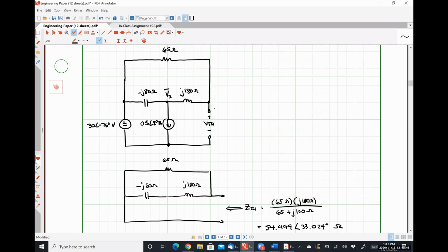So it looks like this is a use of the computer. So which would you guys prefer, nodal analysis or mesh analysis? Mesh, all right. Andrew, you said mesh, right? I'm going to pick on you and make you write our mesh equations. So let's call this mesh A, this mesh B, and this mesh C. So first things first, there is a current source. So what is my current relationship equation going to be?